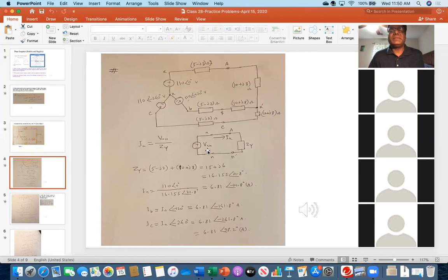So what I have done here, because this is a balanced system, I can make an equivalent circuit like a single phase system from phase A. So as you can see, this is N point, and this is that A point. There is a source Van, which is at 120 degree, and then this A, and then this neutral point. I have put the combined impedance here by the name Zy. This means Y connected system. What is the total impedance? So therefore, for phase A, you could make this type of simple series circuit.